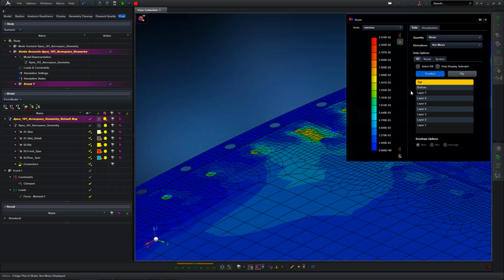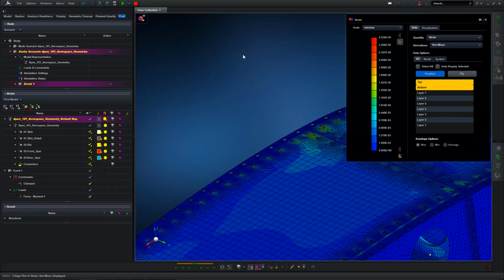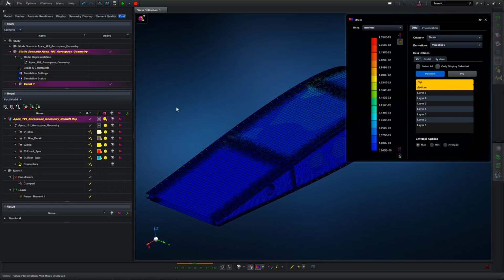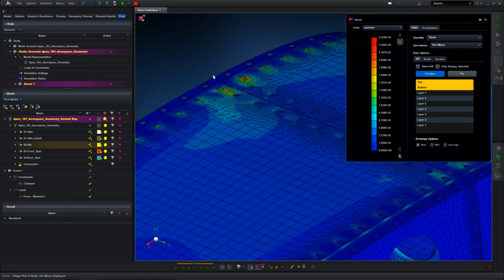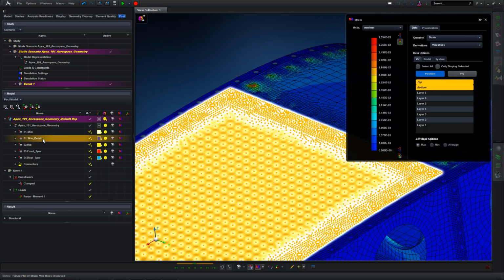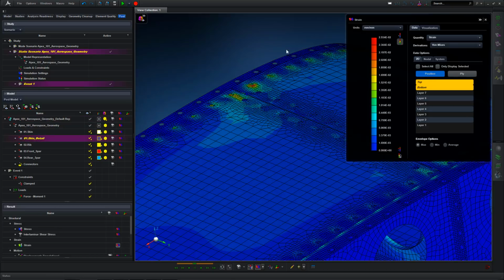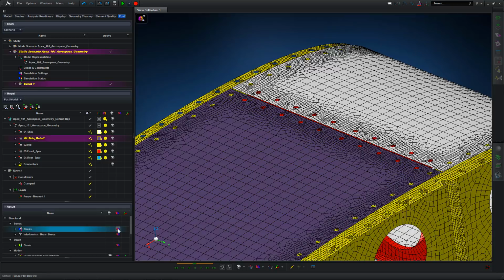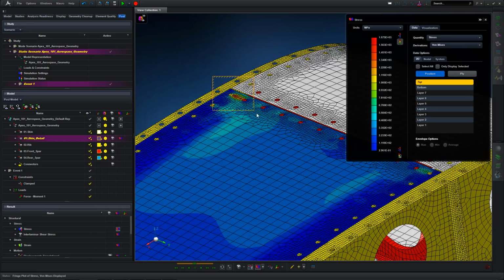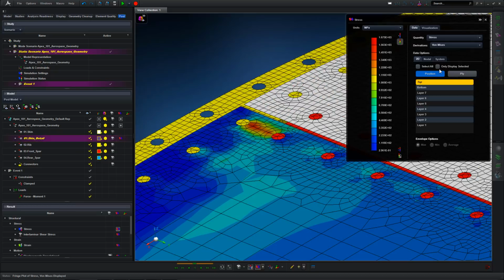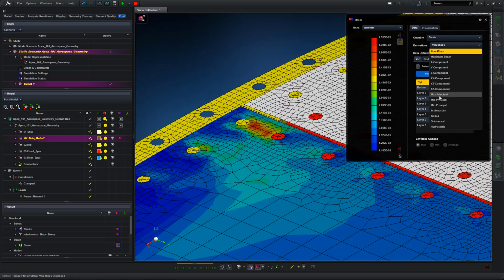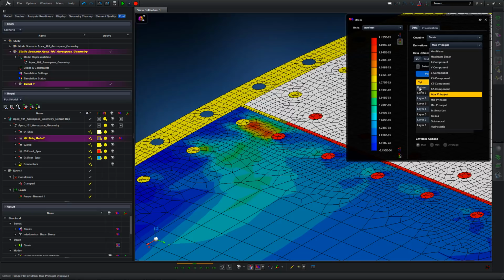So we can see we've got various outputs, so we can look at element strains. So we're showing strain von Mises for the homogeneous top and bottom skins. That's a good marker of understanding what's going on. We're going to focus the post-processing on the skin detail. So by double-clicking on that particular sub-assembly within the structure, all subsequent post-processing will occur just on that entity, and that's useful in terms of any fringe plot output will be reflected, or will be apportioned based on what that particular sub-assembly is doing, so you're not skewed by spurious output from elsewhere.